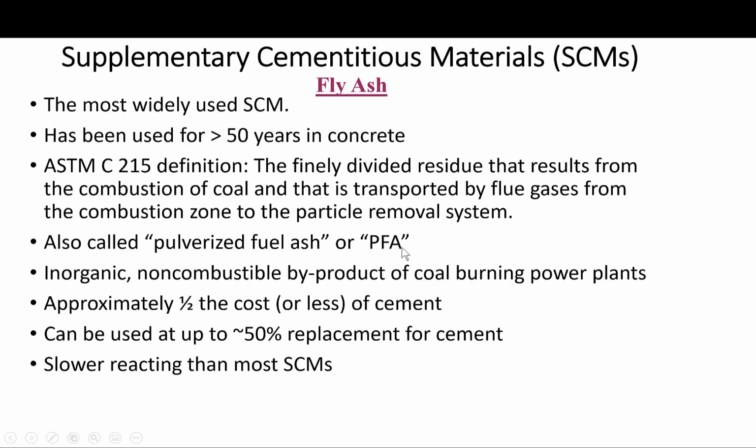It's also called pulverized fuel ash, PFA. It's again an inorganic, non-combustible byproduct of coal burning power plants, as I said. Approximately half the cost of cement or less. It can be used up to 50% replacement of cement, and is slower reacting than most SCMs.